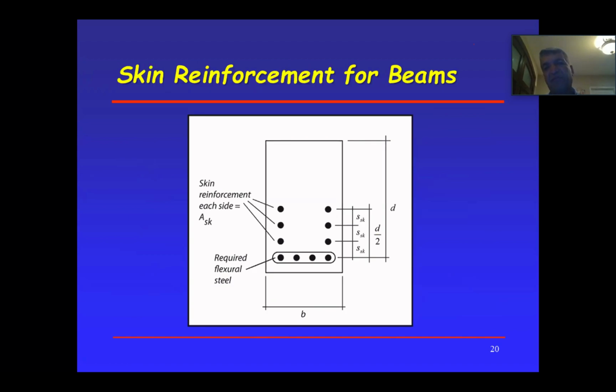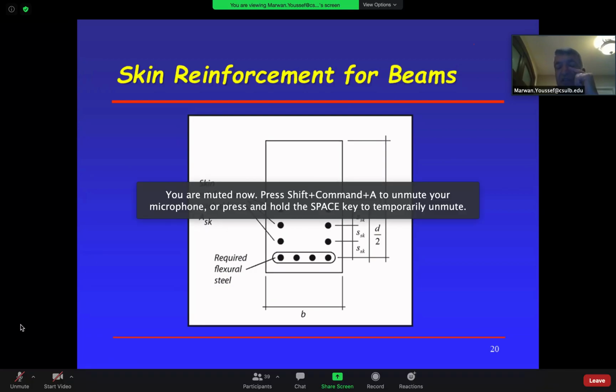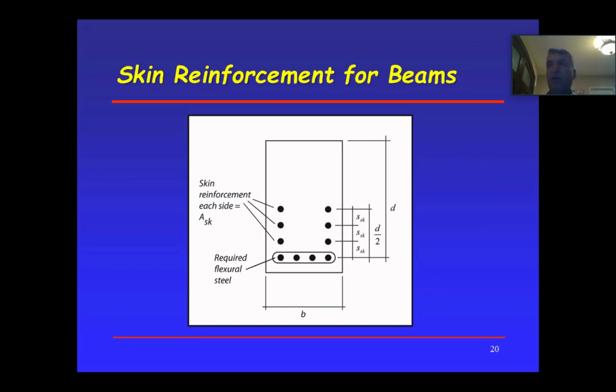In parking garages. Because remember, in parking garages, you're going to have the beams and the columns spaced at about, let's say, 9 feet on centers. Because the parking stall is 9 feet, so they usually put one at each end of a parking stall. Let me get off on a tangent just a little bit here. Somebody could say, why so close? The reason we put them so close, and when you go into parking garages, you look and see, is because the span is very long.